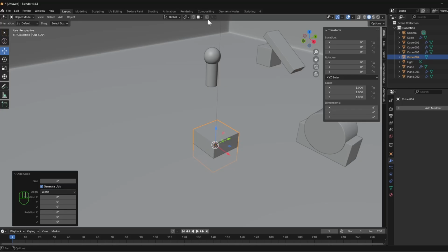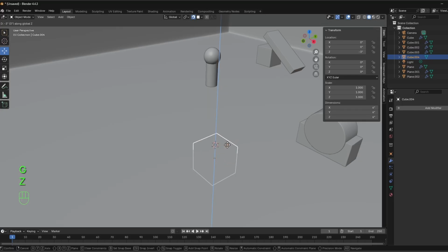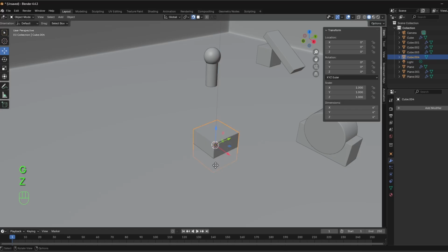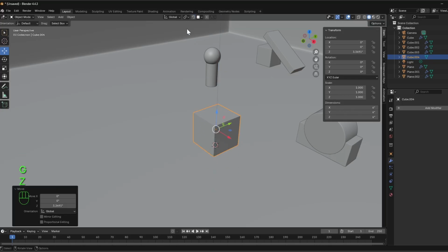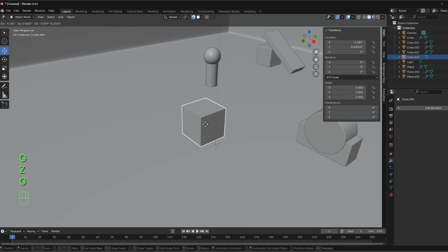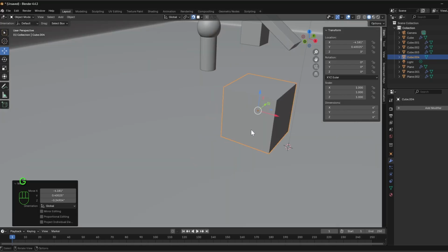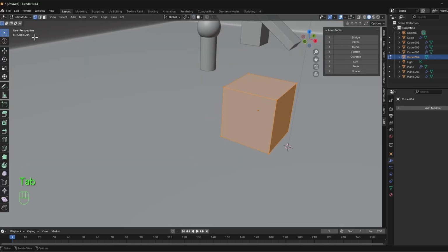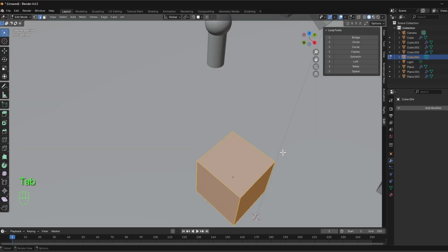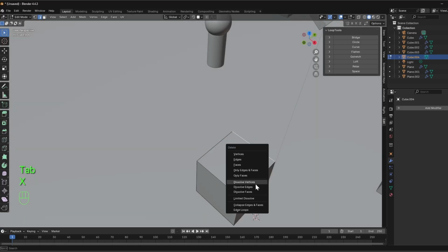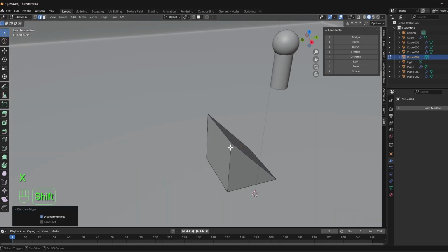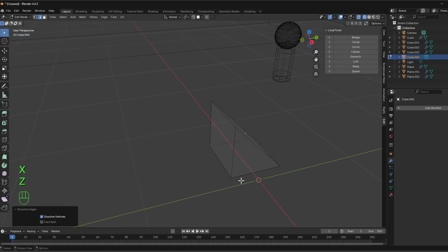Now, I'm gonna create a triangle. Mesh, cube. Make sure to bring up your cube more before you turn on the snap tool. Go into edit mode, select the edge, and dissolve edge. And we're going to add our loop.